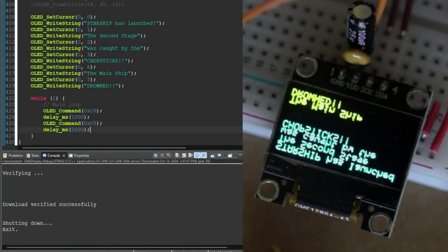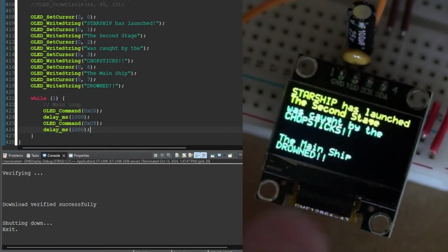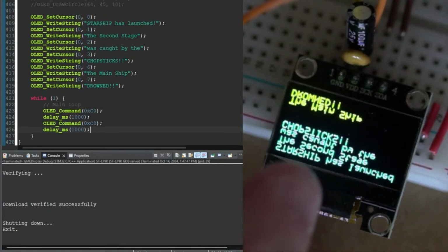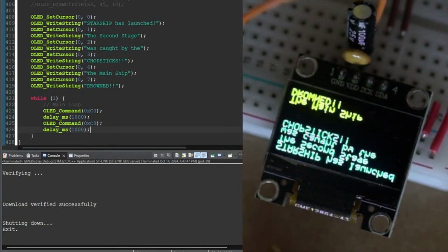And it looks like it works pretty fast too, actually. It doesn't show a drawing of the display every single time. I'm wondering if it uses its own frame buffer to do this, because I do believe that you can opt to use a frame buffer, but I also have this going at 1 megahertz. So this I2C is actually in fast mode plus.